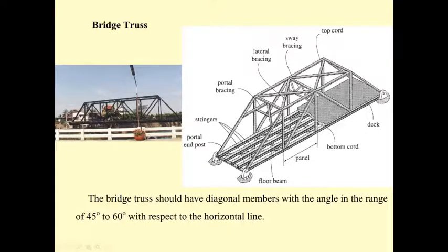As I mentioned, we build the foundation for the bridge, and while building the foundation, you also fabricate the truss in a nearby area, and then use a crane to position the truss onto the foundations, and then we build the floor beams, each of them, to link the trusses, and also we put in cross members to make the truss more stable.